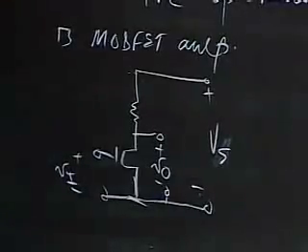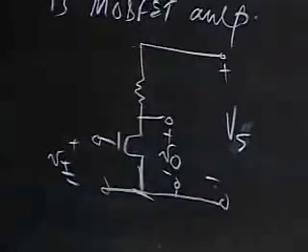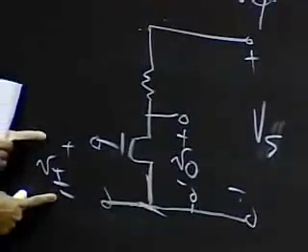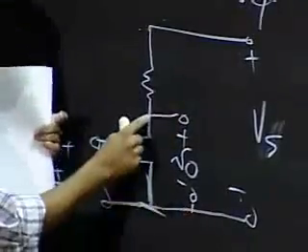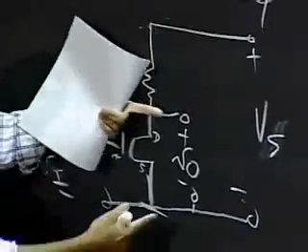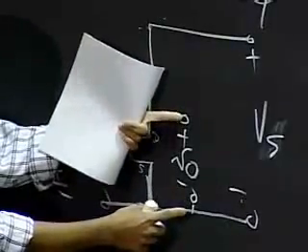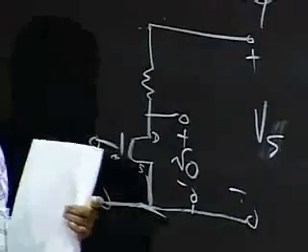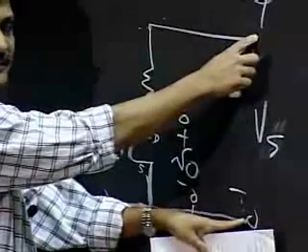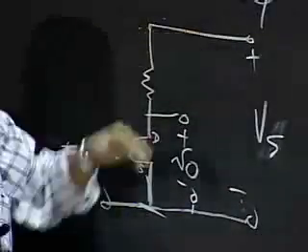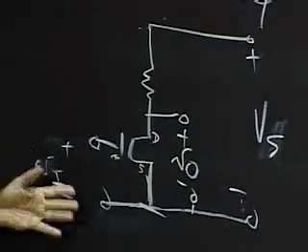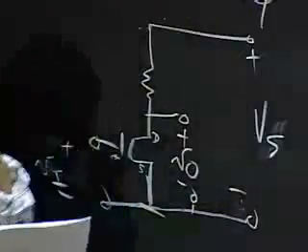And in this, one way of viewing this is that this circuit has three major ports. Okay? This here is the input port with voltage VI. This here, between the drain terminal and the ground, is the output port. So I take the output between the drain terminal and ground. And finally, we have the third port, which is this one. It's called the power port. I apply VS between this terminal here and the ground terminal, and that gives us the power port. So this device here was a three-port device. Okay, input port or control port, output port, and a power port.